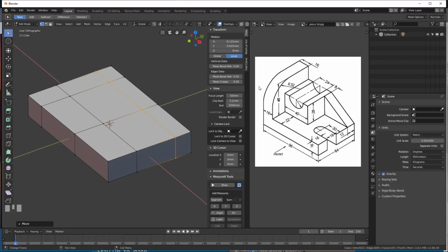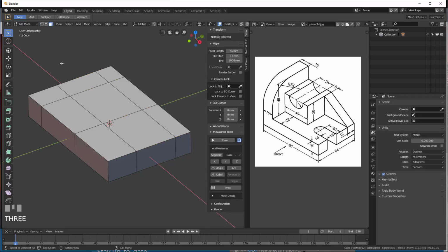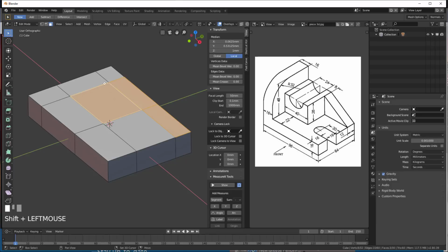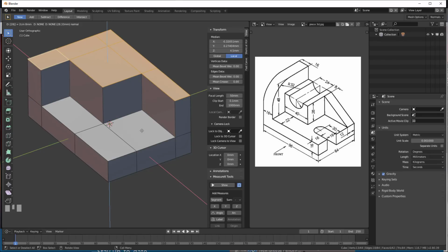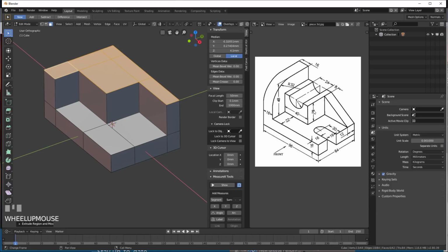And now I have the possibility to extrude all of these parts. So let's go. We will just use the 3 shortcut here, not in the numpad, in the normal keyboard place. So 1 is for vertices, 2 is for edges, and 3 for faces. So now I will just select here with Shift select to have a multiple selection. Okay, so Shift left click, not like before, Shift right click, and we will make an E. And this, we see that we need a 28 height here, that we have here, okay?